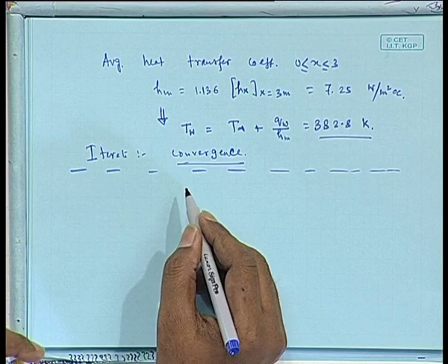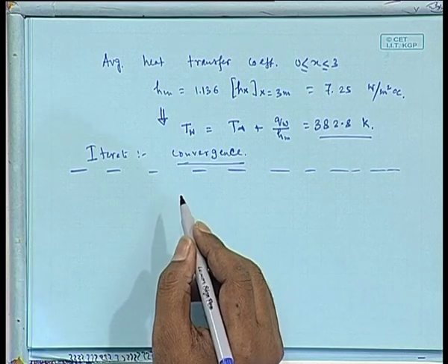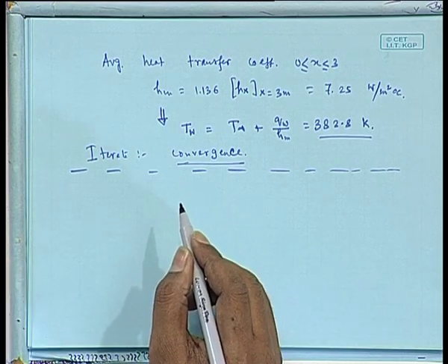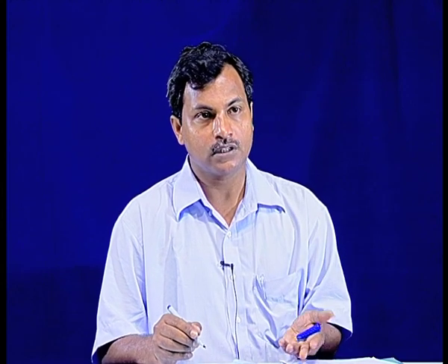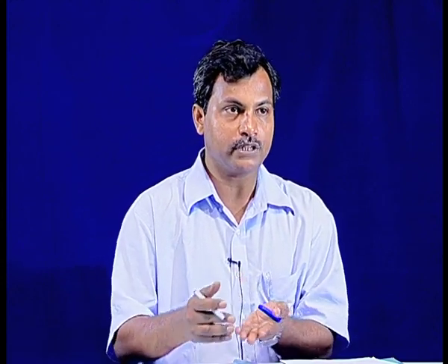Now till now whatever we have done, we have looked into how free convection correlations will be developed and can be used for calculation of heat transfer if it is a semi-infinite plane, open to one end. Now you can have free convection in an enclosure. The typical example is a flat plate collector, where you have two plates and in between there will be some air, with top plates placed one above the other with a gap in a solar panel, all those flat plate collectors.